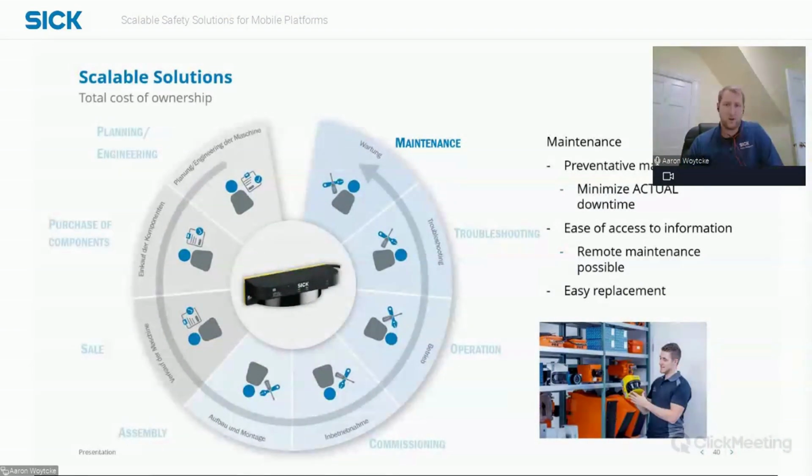First, you want to look at preventative maintenance. A vehicle system, including safety devices, may be able to provide data that could signal a maintenance situation before it actually happens. So for example, we used this example previously, but maybe a safety laser scanner has a front lens that's dirty. And the remedy to this is that someone needs to wipe the screen during the next scheduled downtime.